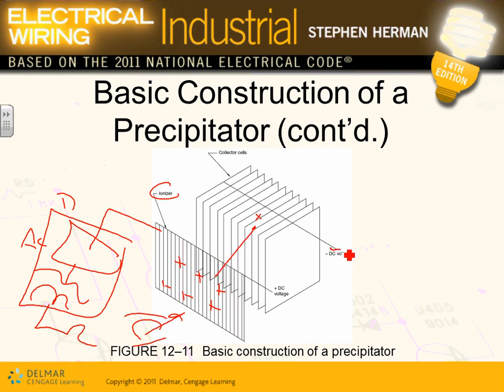So, and this is negatively charged. There's a negative here. So what happens if you have a positive mist and a negative collector or cell? The filter, it's going to attach to the filter. So they charge the dirt, guys, as it comes out, charge it positively, pass it through a bunch of filters that are negatively charged, and they attract to it, electrically attract to it. That's how they collect them.